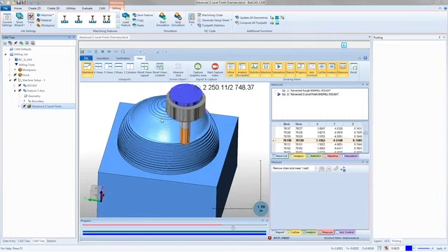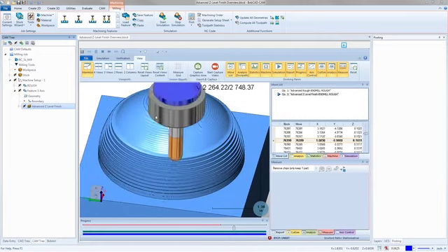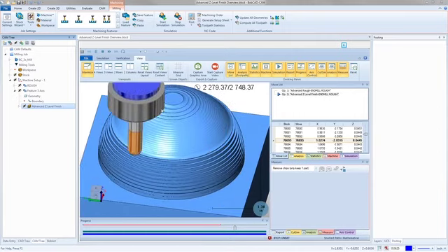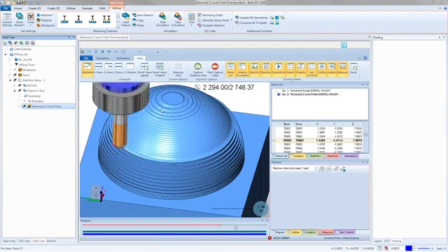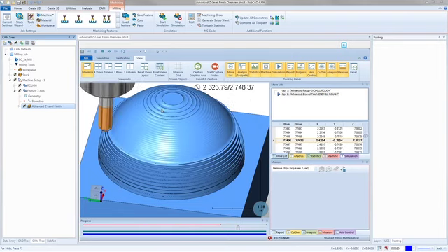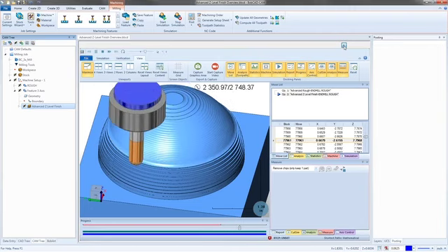So this is what I was talking about, Ron. Right here is the bad finish. And if you make that step over any larger, it's going to exaggerate it even more. The Z level really likes to cut steep walls. The equidistant, though, would have 0 issues cutting that one, and you'd set it up pretty much the same way.